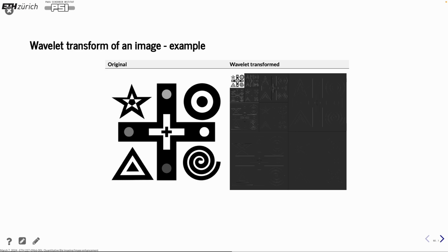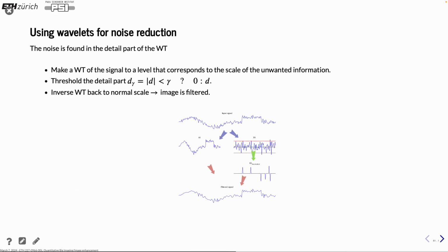And this is a tool in order to get the filtering done, and here is an example of how to do the noise reduction. So what we do is we do first the decomposition to some level. In this case, I only do one level. And looking at the detail, the peaks that go outside of some threshold level will be kept, and everything else will be set to 0. Because the peaks that are going outside, they actually can correspond to some real information. So we want to keep those. The rest, the ripple, we don't want to have, so we just reject. So the new detail image looks like this, and then when we combine it back, you can see that we have reduced the noise quite a lot, but not fully.